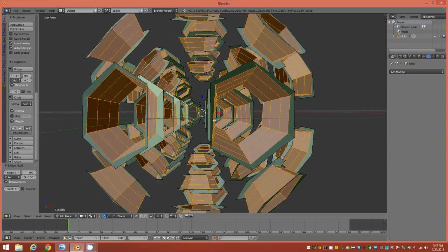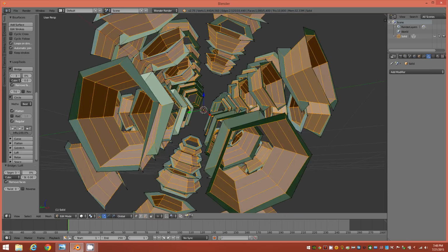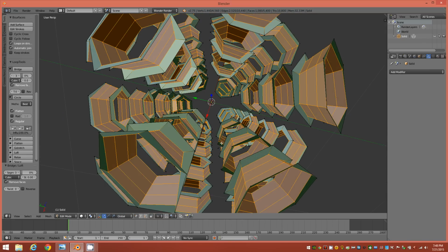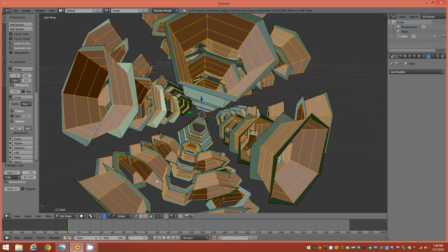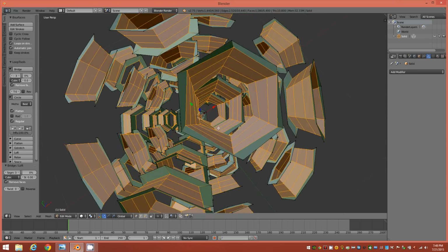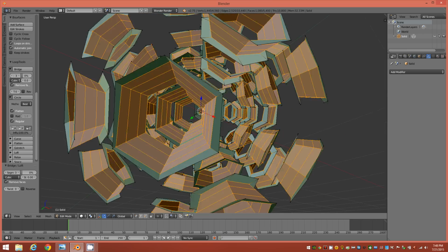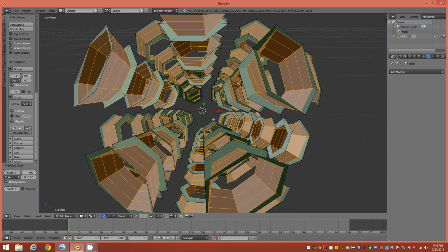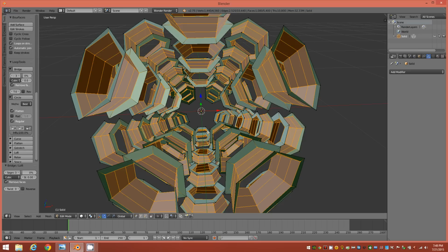That seems to be crucial to getting proper bridging. Tapping it once resulted in some crossed edges and all kinds of topological errors for some reason. So that was a crucial step to getting the proper bridging in here. It must have something to do with the algorithm of the bridge tool. So that's our bridges here.